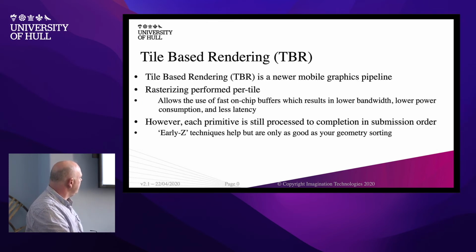But if we split them up into tiles, then you need only a fragment of that frame buffer, so you can then place that on chip. Okay. So actually, you're reducing the latency because it's right next to it. It's basically a cache memory sort of thing. You've got this thing very, very close by. Okay, which is really, really nice.